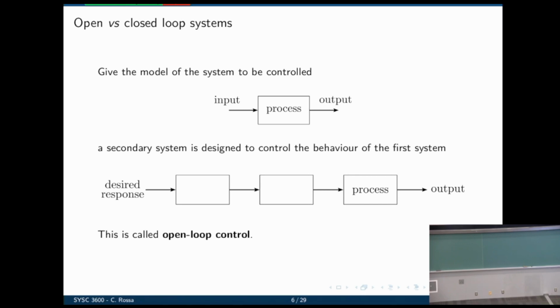Using the block diagrams, you see that sometimes we have not necessarily just a straight input to output relation, but it may have the output being fed back into the input to the system. And this is very common in physical systems, in nature, when you have some sort of feedback, some way to observe what is happening in the system, and then use that information to create a logic to control that system.